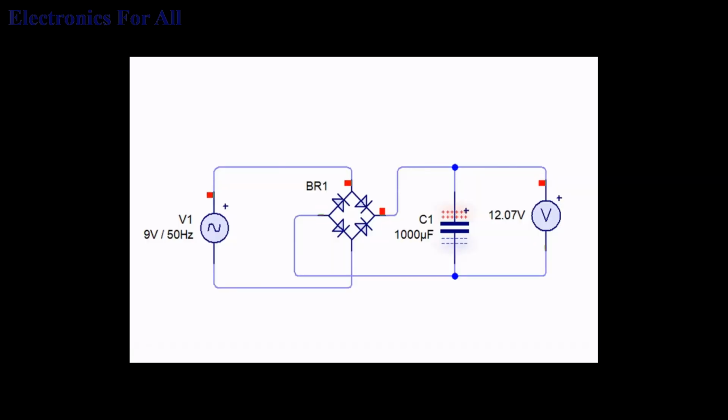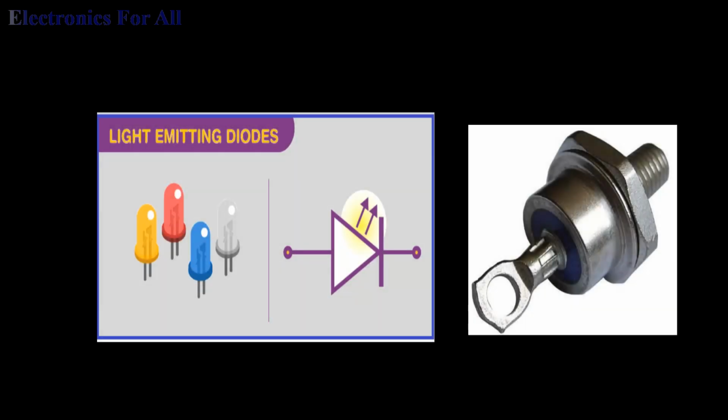Whereas the off mode of the diode is attained with the aid of reverse biasing, which simply means that higher or positive potential is applied on the cathode and negative or lower potential is applied on the anode of a diode. In the on situation, the practical diode provides forward resistance. A diode needs forward bias voltage to get in the on mode. This is known as cut-in voltage. Whereas the diode initiates conducting in reverse biased manner when reverse bias voltage goes beyond its limit, and this is known as breakdown voltage. The diode rests in off mode when no voltage is applicable across it.